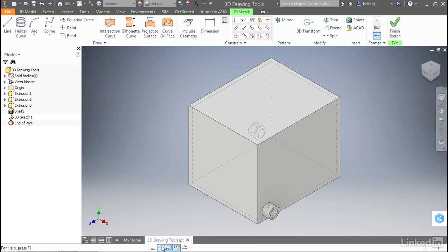Let's make sure we uncheck all of these. You'll probably have them all enabled by default, which is fine. But for this demonstration, I want to start with none of them selected so that you can see what each does as we enable them. We're going to start by right-clicking and selecting 3D Line, and you'll see a new UCS is presented. As we move the cursor around, you will notice that we can align to each of the axes. But in general, at this point, with none of those options enabled, we're really just clicking around in 3D space. You'll notice that if I hover over the model itself, nothing highlights, only the axes highlight.